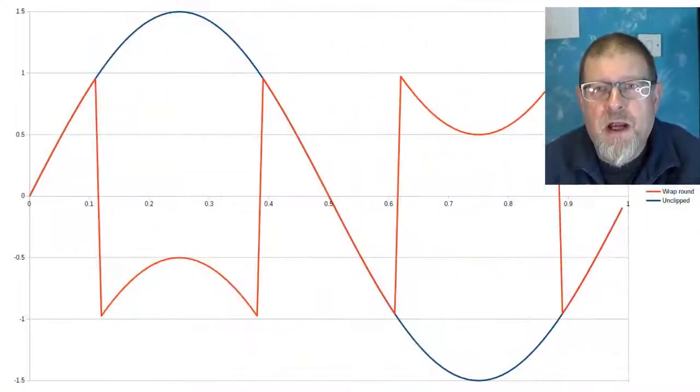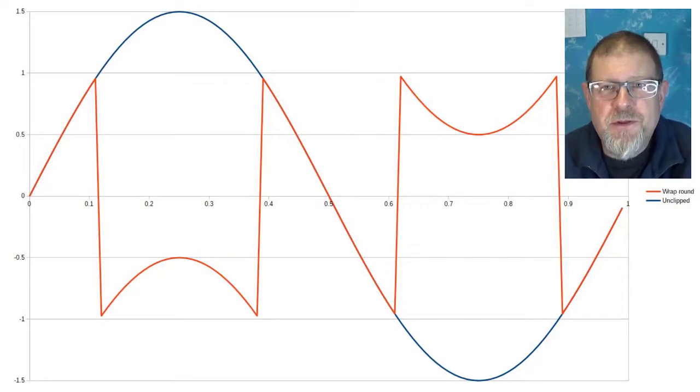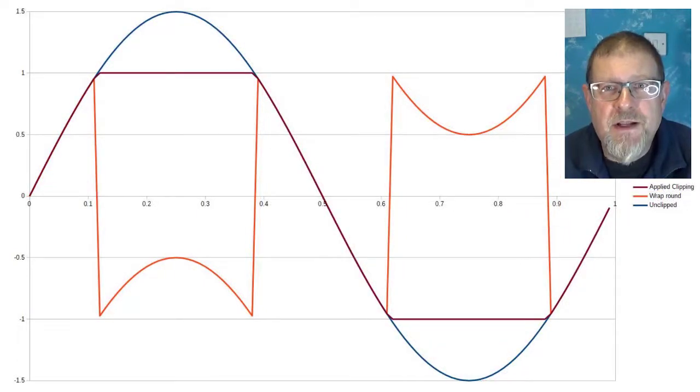In the digital domain, however, clipping does not naturally occur, and the numbers wrap round from top to bottom or from bottom to top. This sounds terrible, as I'll show in a minute, so to prevent this we have to make sure, if our calculation results in a number that exceeds the maximum value for a sample, we actually take steps to clip it ourselves.